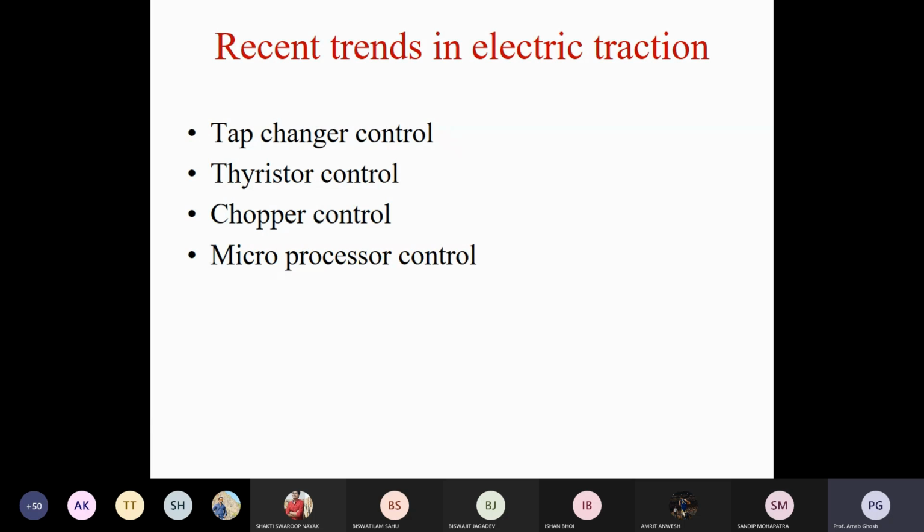In case of a motor coach, when you are taking electricity from the overhead connections through the pantograph, one transformer is situated inside your motor coach. What is the purpose of the transformer? That transformer has three LV windings and one primary, so it is a four winding transformer. One HV winding and three LV windings. One LV winding is dedicated for your traction purpose.